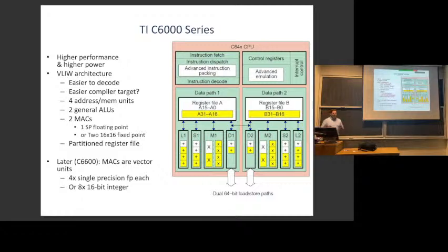So that's a bit more inconvenient for the programmer, because if you wrote assembly code for this by hand, you have to remember these registers can feed this multiplier, and these registers can feed this multiplier. But it's a way of getting less centralized state. In the first lecture, we talked about how in a processor, if you put everything in a register file, everything in a big shared memory, it's very easy to program, but big register files take a lot of power, a lot of area. So they partition it and tell the compiler about that, and it gets them somewhat better power efficiency.